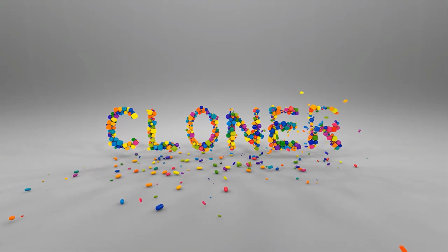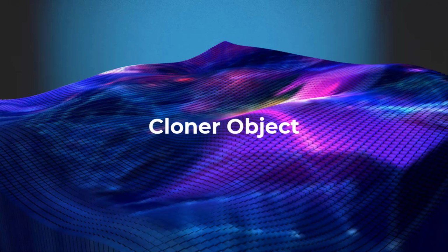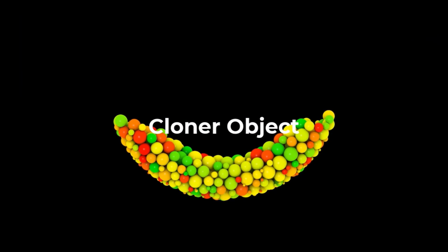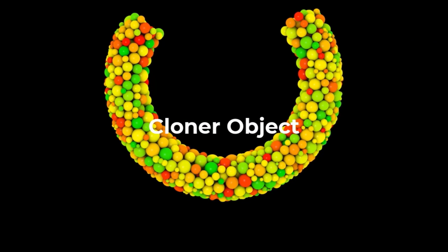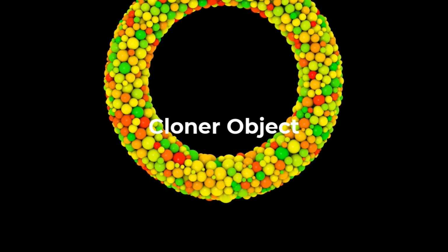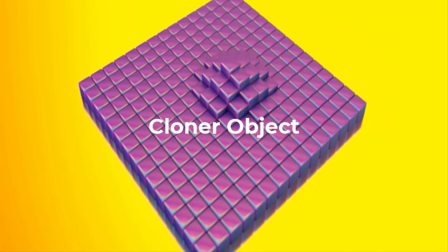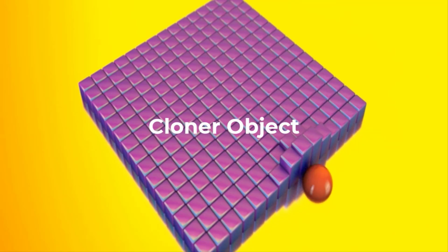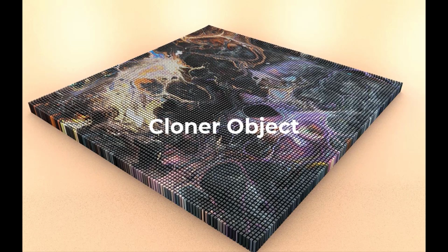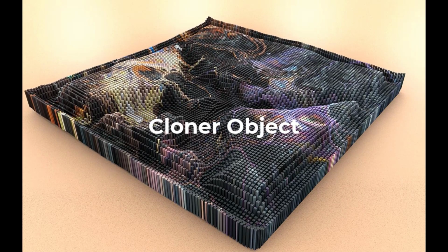Now I want to show you a really cool and powerful object in Cinema4d called the cloner object. It is the object for the duplication of other objects, arranging clones onto vertices of other objects as well as splines. The cloner object sets your object up so it can be affected by various effectors. Let's do a demo.